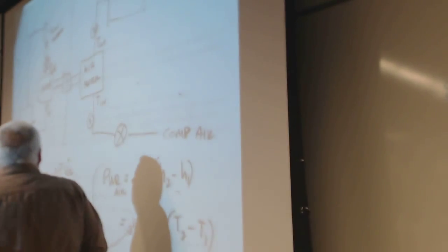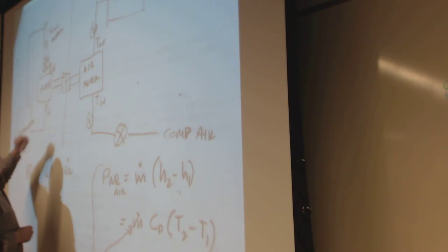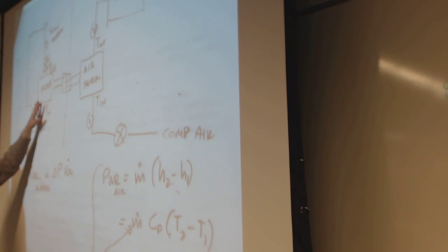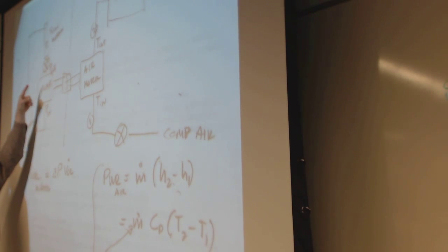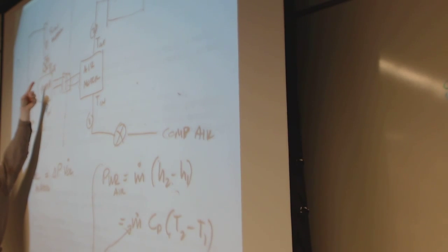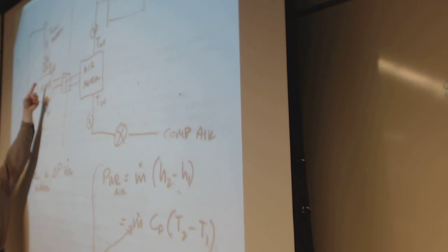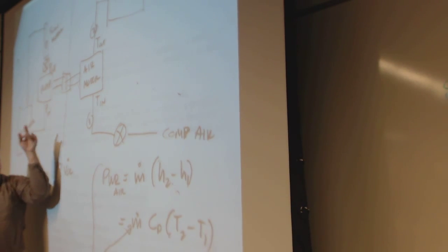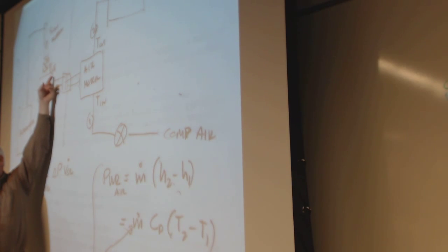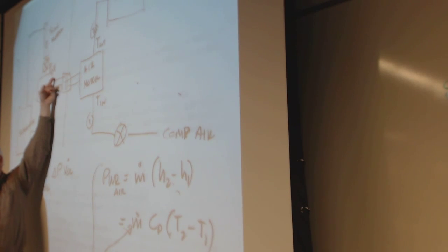So you're taking pressures here and pressure there. Do we care about the temperature of the water? Not a whole lot. It would affect how the flow meter is calibrated if the flow meter was super crazy calibrated, but for approximate room temperature water, it doesn't make a big difference. So we don't worry about temperature on the water.